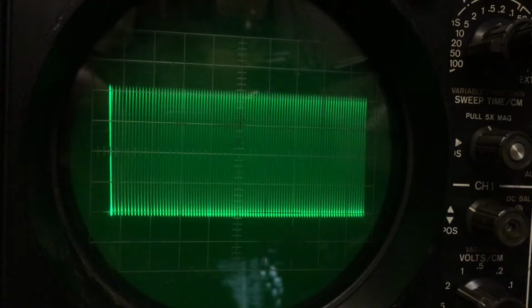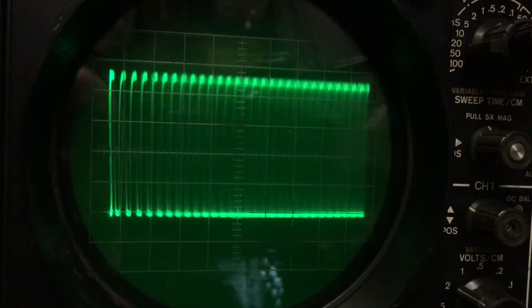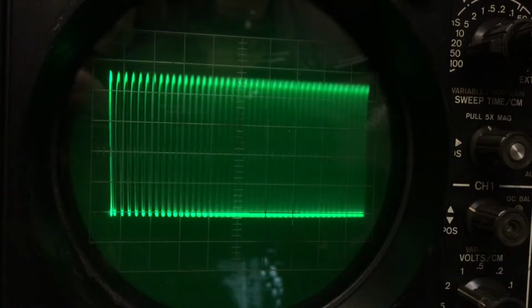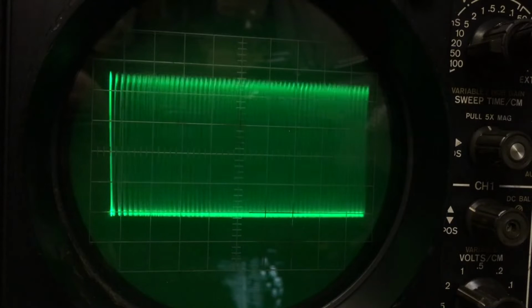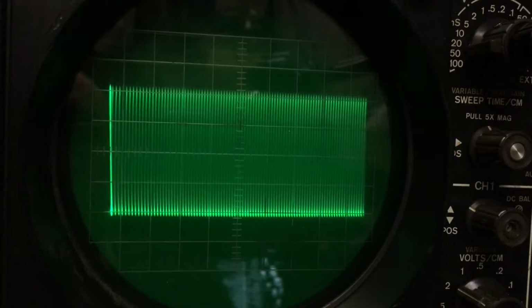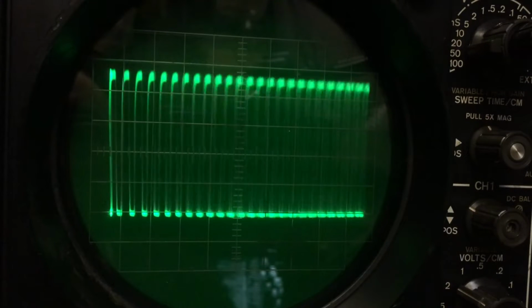We can see right here if I take a square wave and sweep it up in frequency and feed that into the front end of my ancient 10 megahertz hobby scope. As I turn the sweep knob back and forth at like 10 megahertz or something, I don't remember what this is, you can see the wave changing in amplitude and changing in shape as well.